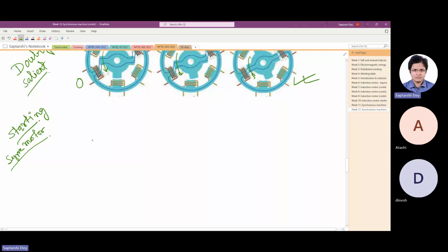Synchronous machine. Now you have a synchronous motor, you have a grid, and you connect it to the grid and close the switches. Instantly, what happens? Instantly, the stator field starts rotating at the synchronous speed, which is given by 120f/p. Maybe in India 3000 rpm for 2-pole machine, 1500 rpm for 4-pole machine, and so on. So the rotor was static, a heavy metallic rotor, static. Suddenly you ask it to rotate at 1500 rpm.